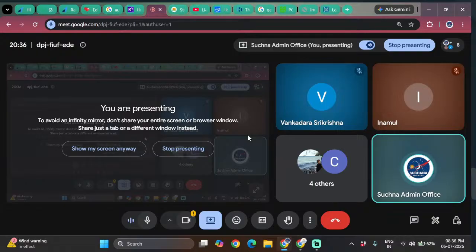So any questions up to here? Today we discussed visual inspection and IPC and its history, why they are followed, what the advantages of following IPC specifications are, the visual inspection test, and then the common rules we should follow if we are using gold fingers, like 45-degree chamfers and not using sharp edges. It should have some inclination, measured in the anti-clockwise direction, and the result should yield a standard value of 45 degrees.